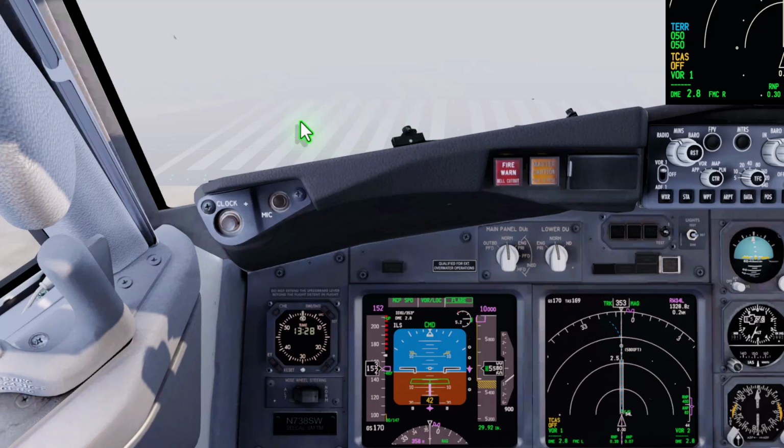Now, in this simulator model, this is a little bit different than what you'd see in the real world. This is the end of the runway. In the real world, it's going to take you down to the 1,000-foot point. This is just probably a simulation condition here. But what you're going to see is the touchdown zone on a real Cat 3 at about 50 feet, 40 feet, but it's going to be a solid line here.